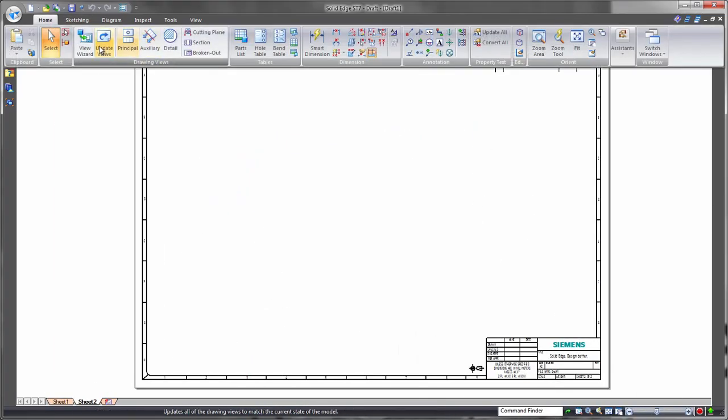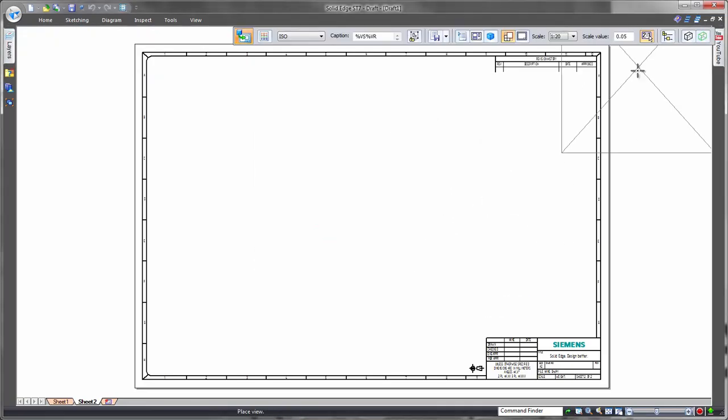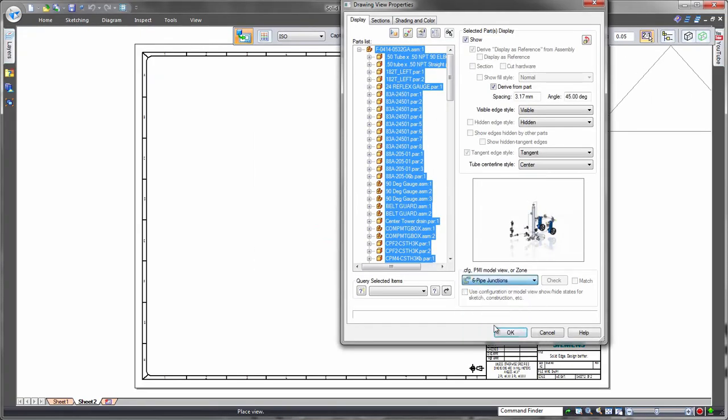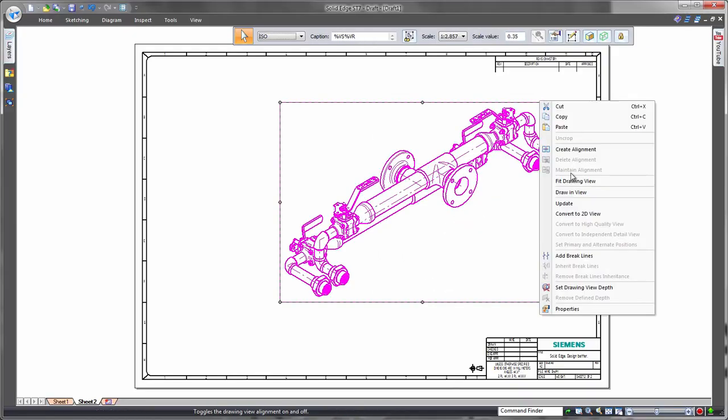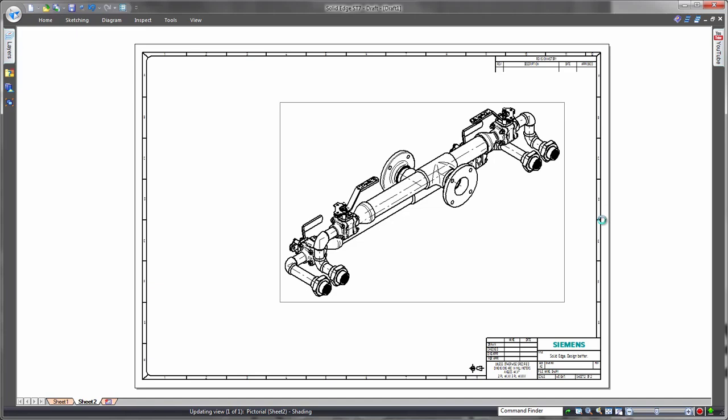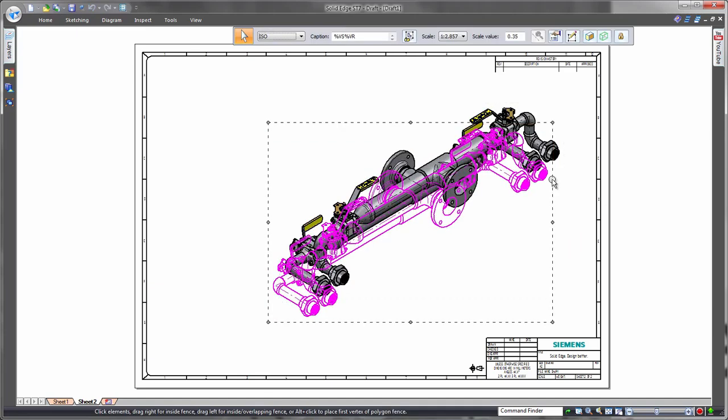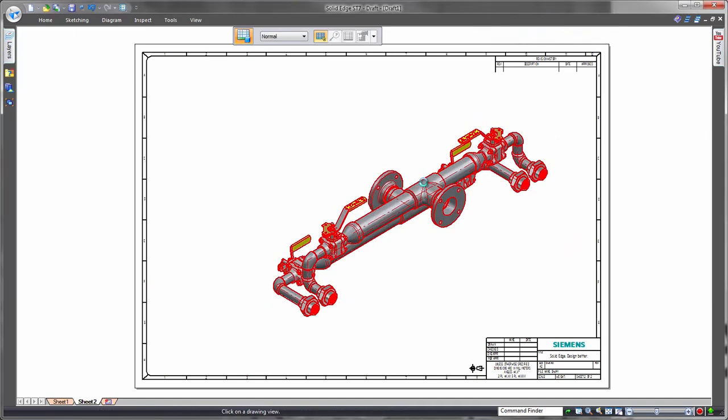We'll represent a single piping section from the vapor recovery assembly on a second drawing sheet. Select one of the assembly's display configurations, and the view is populated with that section's relevant equipment and routing. Final pipe cut length information is highly valuable in determining exactly how much stock to purchase.